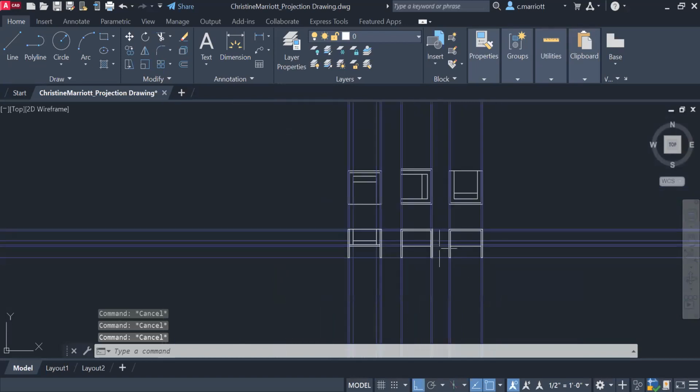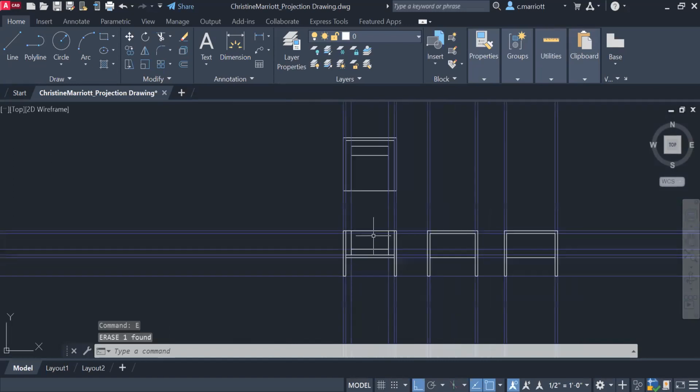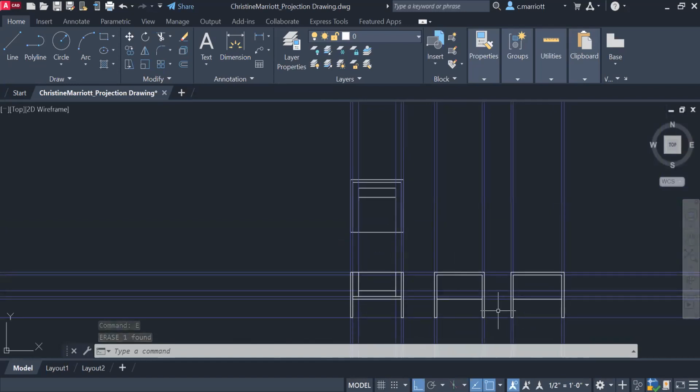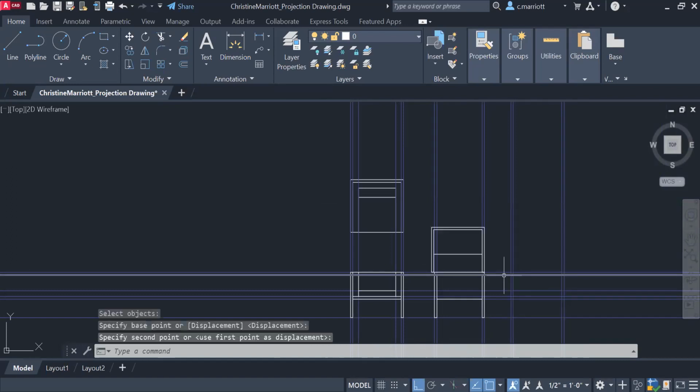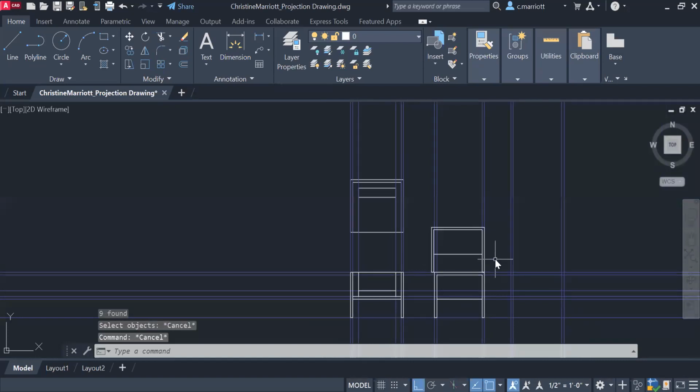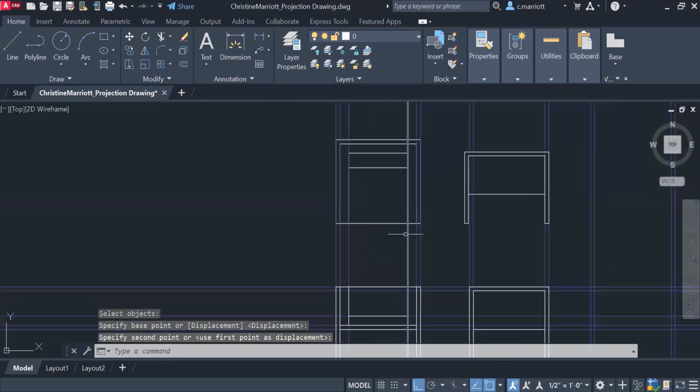And those are the 3 side views, all right? And I've got these extra chairs. I don't need them. I only need one plan. And what I want to do is arrange these kind of in a 4 square. So I'm going to move this. Where should I put it? Here, and then I'm going to move it again. Now just watch how I did move P for previous, and it picked all of those. And I will move it so it aligns with the bottom of this.